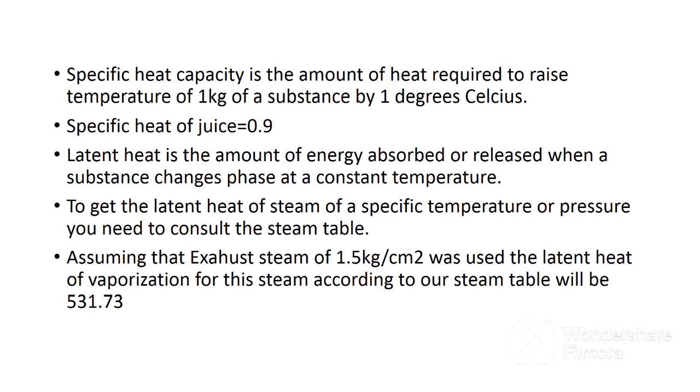Latent heat of vaporization of steam varies depending on its temperature or pressure. So to get the latent heat of steam of a specific temperature or pressure, you need to consult the steam table which I have attached at the end of the video. Heating without vapor bleeding system uses exhaust steam of the same pressure, hence latent heat of vaporization will be the same for all juices.